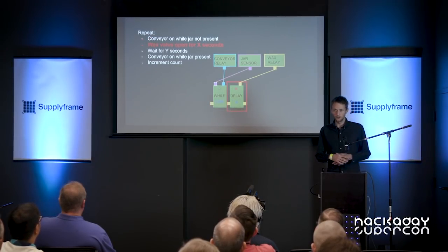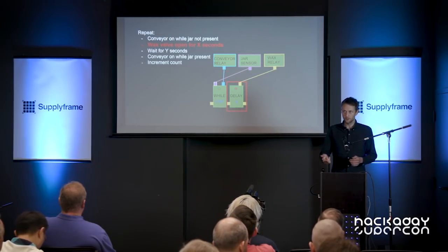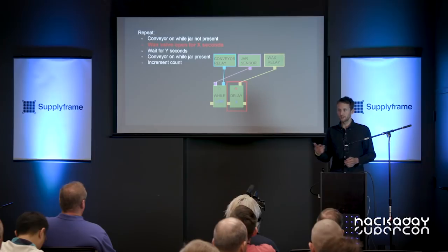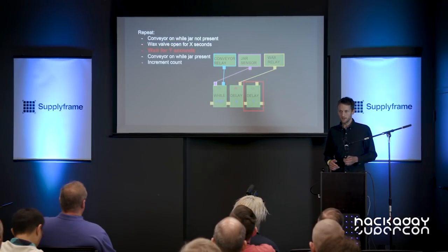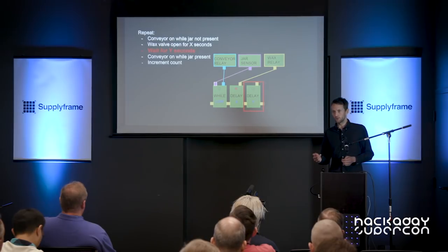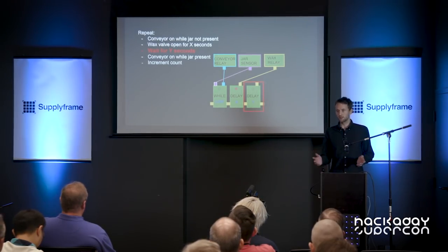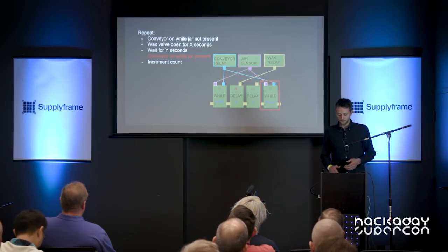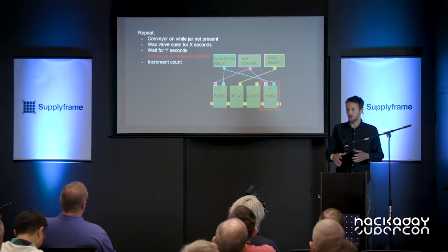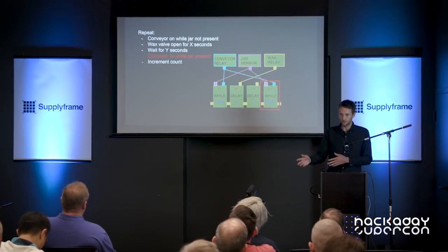Next step is to delay. This allows us to configure the wax dispense time. Connect that to the wax dispense relay. And then we need to delay again for the dribble. So that's an optional delay, connected to nothing because it's only responsible for just waiting there a bit. And then we need to move the jars that have been filled out of the way of the conveyor, or out of the way of the sensor.